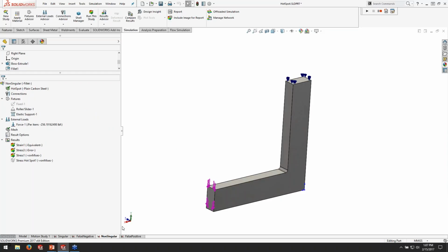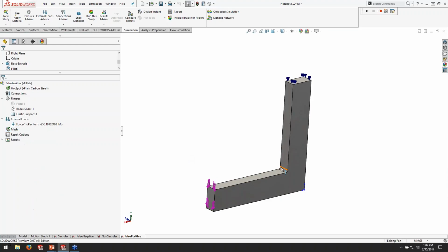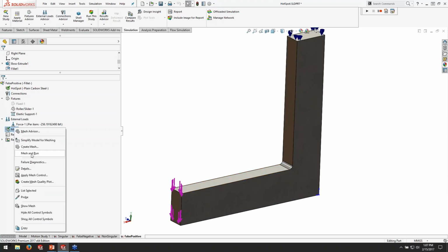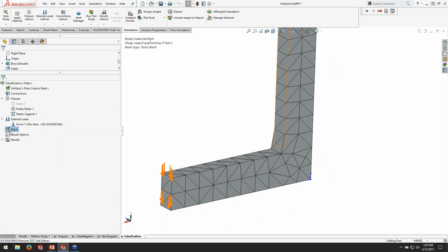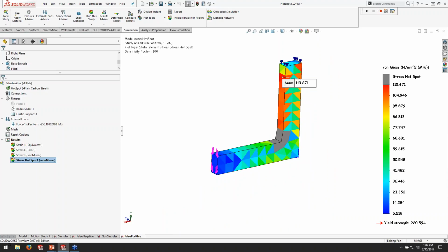With some trickery, you can get it to read false positives and false negatives, but these are very particular scenarios. Like here, I was able to get it to read out a false positive. If I have this fillet here and I mesh right over top of it by using the tolerance, so if I somehow get the mesher to go right over it, then the stress hotspot tool will report that as a singularity. So it does give me a sort of false positive there, but I think it does a pretty good job even in this scenario of identifying the correct singularity areas or not.